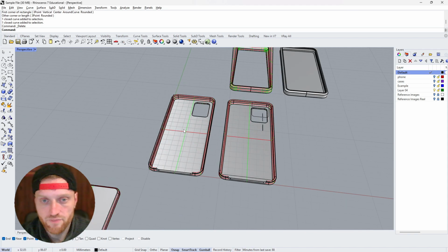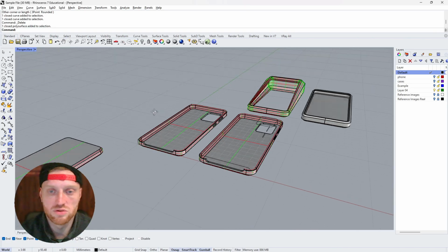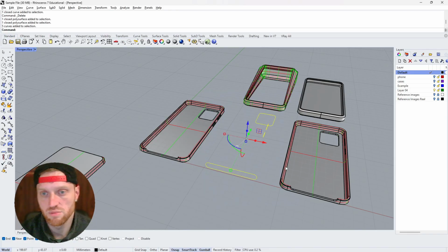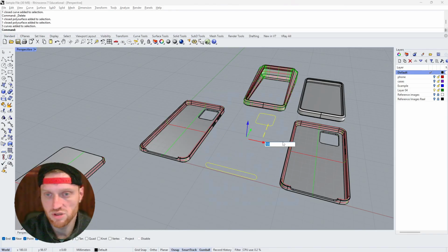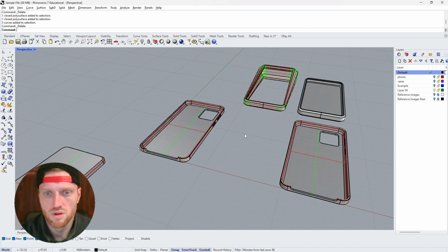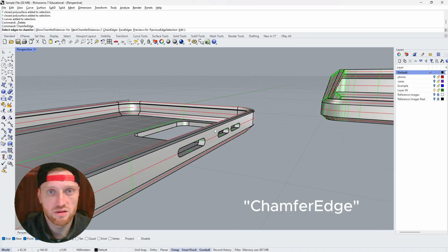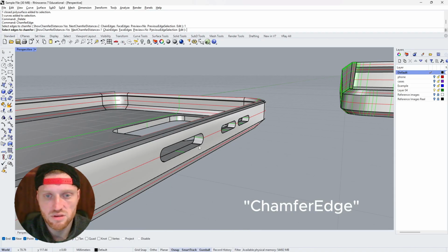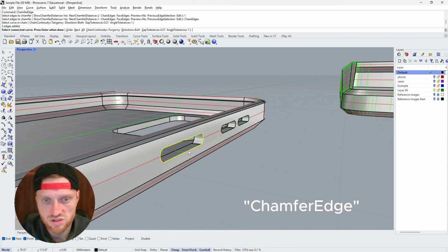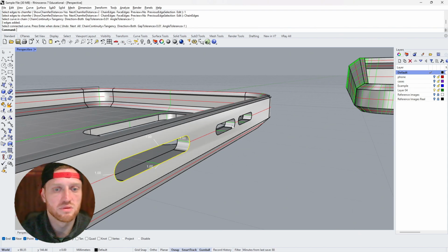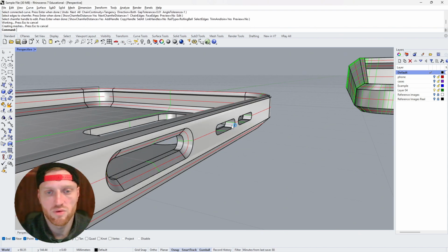All right. Now, maybe you want to refine things a little bit further. Let me select those, or maybe I will get rid of them. I would say maybe do chamfer edge again, 1 millimeter chamfer edge, and I want to just give these some nice chamfer, right?